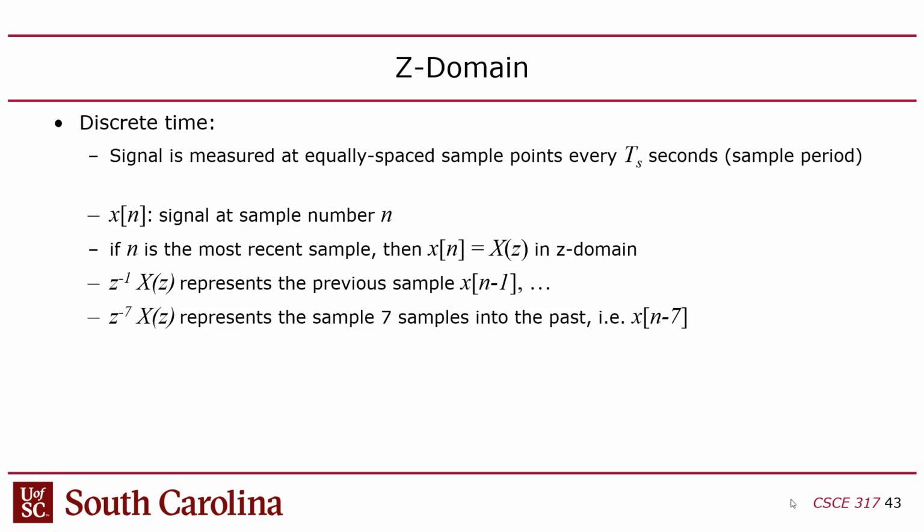If you want to build this with a computer, it has to be in the discrete domain, right? Now, in the discrete space, you introduce another parameter to this whole thing, and that's called the time step. It's basically how fast your computer is, right? How fast does it recalculate the control law? How fast does it implement? And for that matter, by the way, even the control law in the S-domain, you can't directly implement the S-domain.